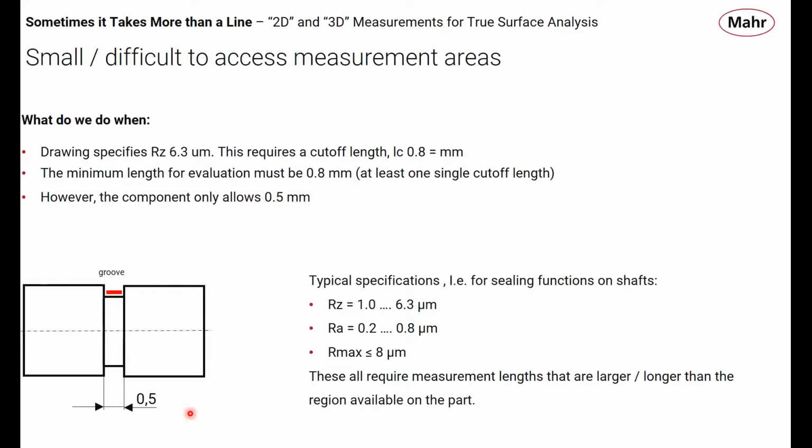So a single half a millimeter long trace with a stylus, I would argue, is probably not the optimal technique for this. The data density is just not high enough for me to be confident that you're really representing that surface. There are absolutely arguments against what I'm saying, but that's what I'm proposing to you right here.